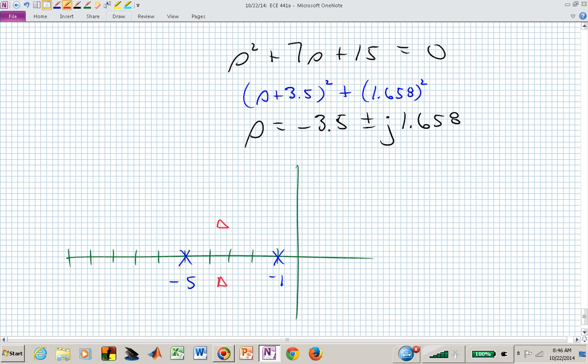Now those poles, this guy has gone here, and he went from 2.5, and now he's gone up here, and this guy is doing something like this. They actually come together and they meet. They don't like to spend a lot of time together if you're adjusting the K and they go off the real axis. But that shaded line of yellow is actually our root locus. As we're cranking up the gain K, K moved from 1/2 to 1. We moved from 2.5 and 4 to this now imaginary or complex pair of poles.